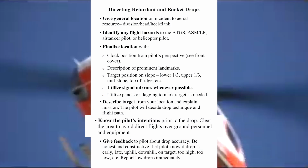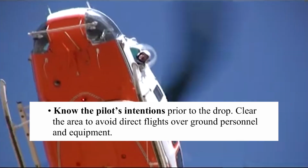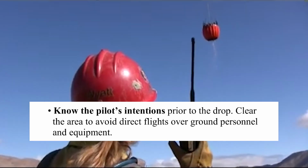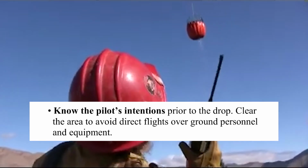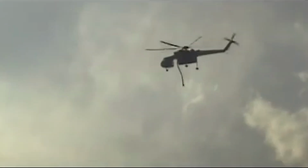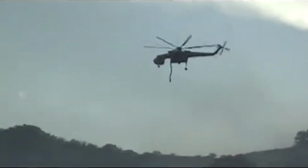Know the pilot's intentions. You must understand the pilot's intended flight path and drop technique. Clear the drop zone fully to avoid direct flights over ground personnel or equipment before you inform the pilot that the drop zone is clear. Dropped water and rotor wash can break branches, topple trees, and dislodge rocks, logs, and other debris which could roll downhill. Be aware of gravity hazards and clear the drop zone well away from and below the target.